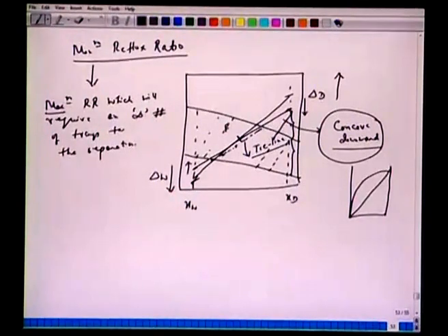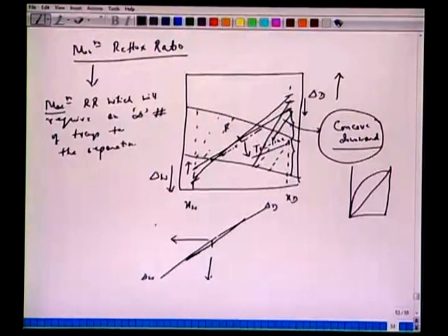Otherwise, there is a possibility that we have some other tie line which might give a maximum reflux ratio greater than passing through this. That rarely happens, when we have situations like non-ideality, azeotropic distillation, etc. So, for the time being, this is for our calculations. We are finding a tie line passing through this F, which is coinciding with del D and del W line with feed somewhere here. Okay.